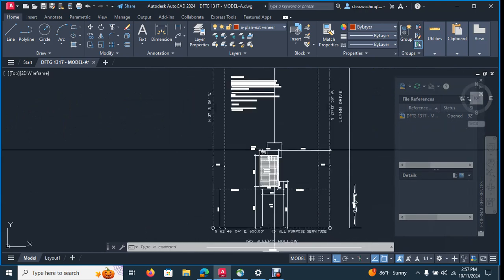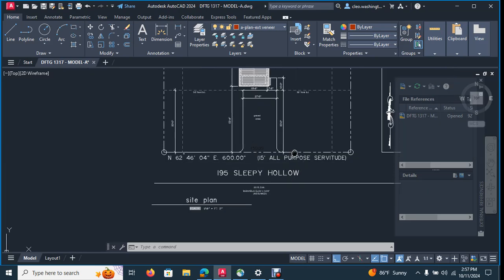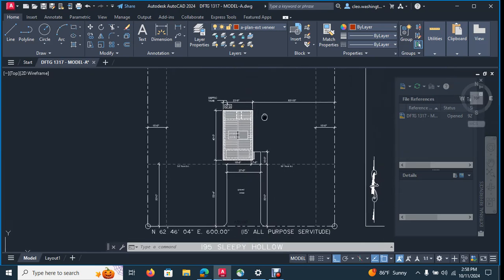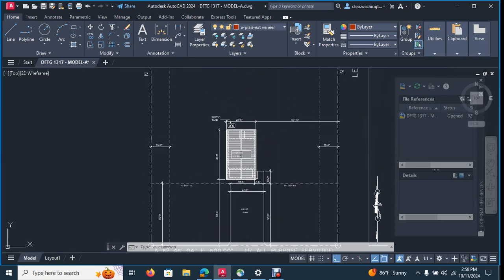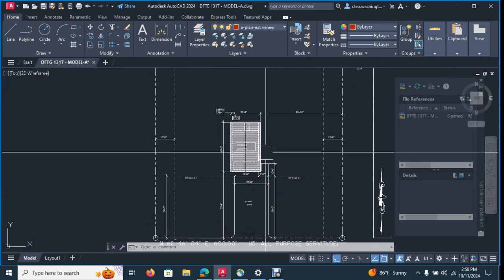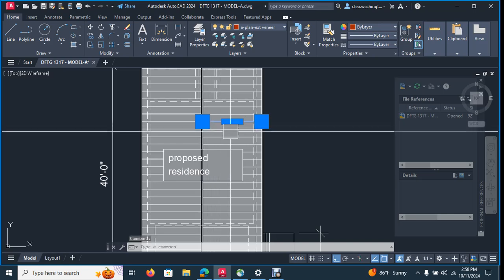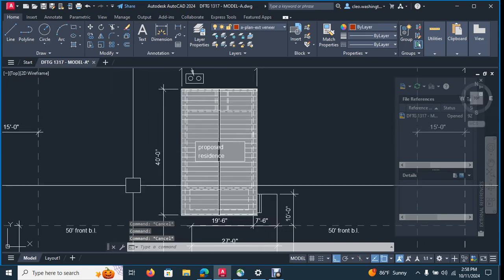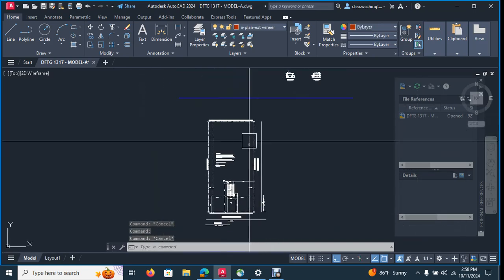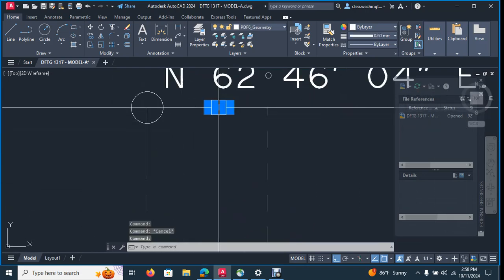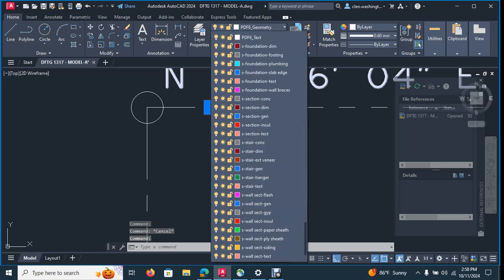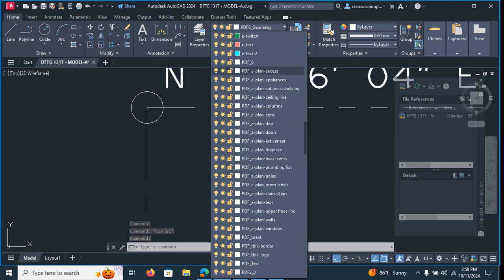Okay, so let's go ahead and apply layers, and after we apply layers, we'll take our building and place it on the site right here. So let's leave it right here for right now, but after we get our layers applied, we're going to take this off of the site. Okay, so first things first, this is a property line. Typically there is a layer that says property.